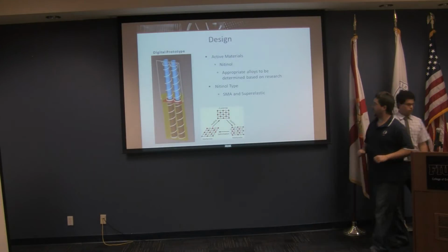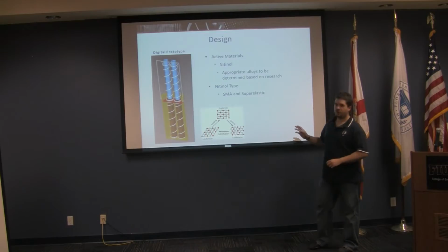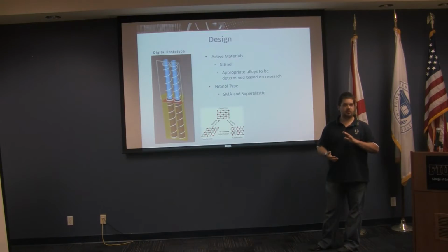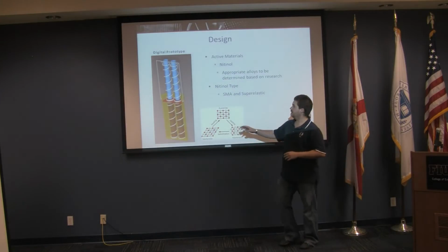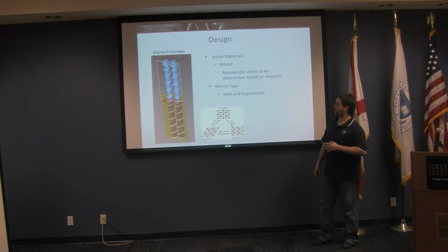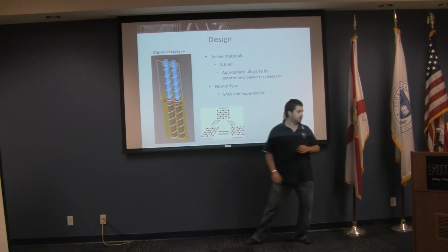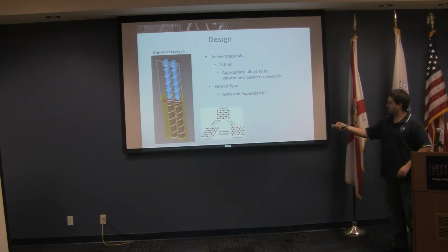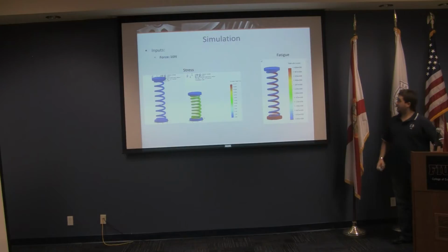Actually, I want to add something. One of our design goals was to make a shock absorber that would retrofit, if you will, the current shock absorbing systems. So you should notice that the main housing is the same shape and style as the tubes that are in use now, and we have guide rods that we implemented here to prevent buckling, and we also have a plate right here, which is basically the mounting point for the springs for the top and bottom. And the bottom tube moves relative to the top tube, so everything moves in tandem. So I want to add that.